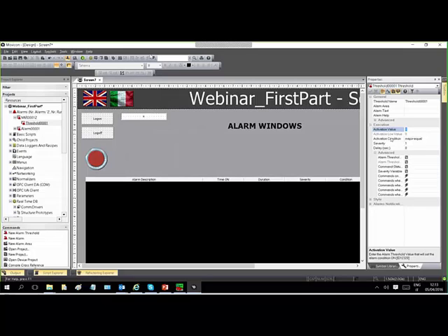Now it's done because on my variable I have associated the alarm. The description will come from the string table, and just for simulation purposes, we could add, let's change the color to say that it is a different type. Here I'm toggling the variable 70, refresh 70 dot 0, the first bit on off.